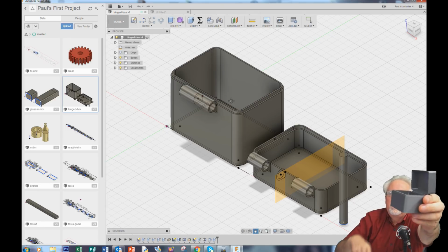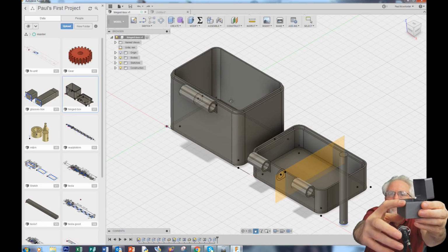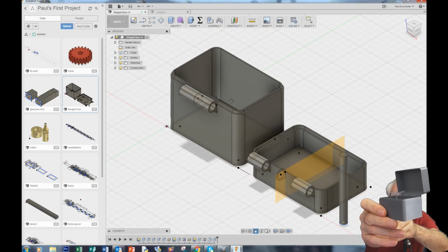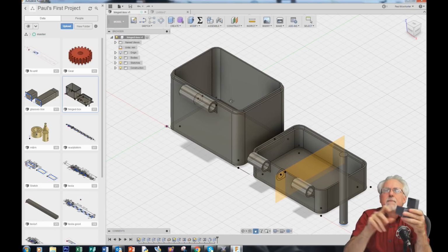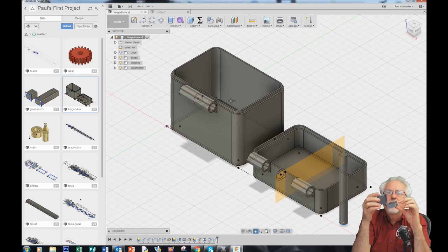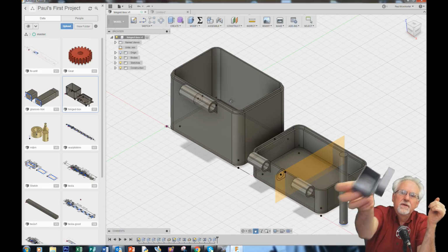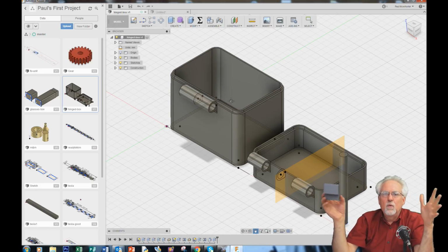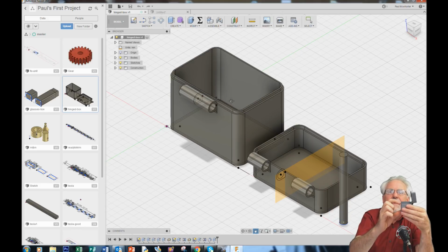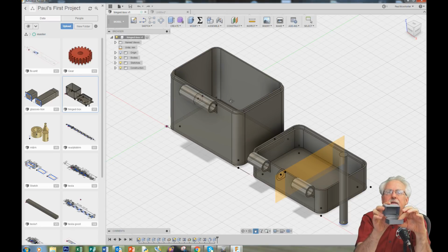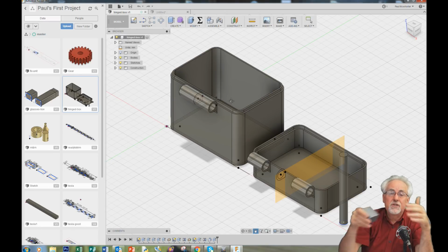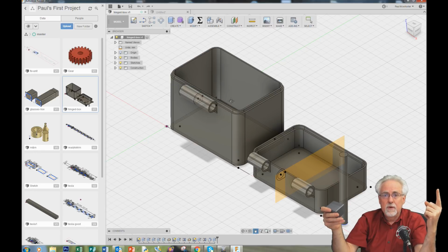What else do I have? Do you see how I have a little lip on there? Can you see the little lip? Okay. There is a lip height on the bottom, and there is how far it's recessed on the top. That dimension, is that 1 or 2? That's 1 parameter, because if this little lip gets taller, this little lip here better get deeper. You always want them to match. So lip height is 1 parameter.